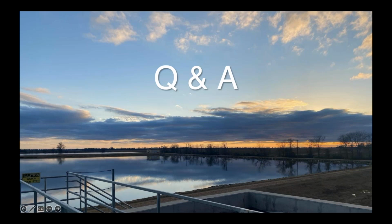There's a question about what the HRT is for different types of wastewater lagoons. If I take it from the slowest to the fastest, for facultative lagoon systems you typically see about a 90 to 100 day retention time, 120 potentially. Up in Canada, it might be 150. It's really dependent upon the temperature and the average seasonal temperatures. If it's cold, the lagoons are slower.